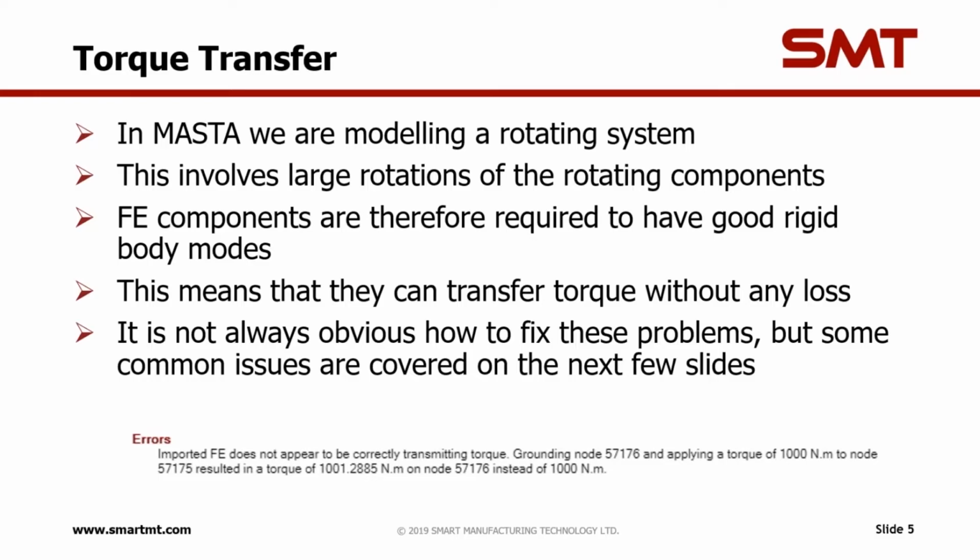It's not always obvious how to fix these because it can get quite into the details of the FE theory, and it can be quite sensitive to which particular FE program you're using. But we've tried to cover a few of the common problems that we see in support questions in the next few slides.